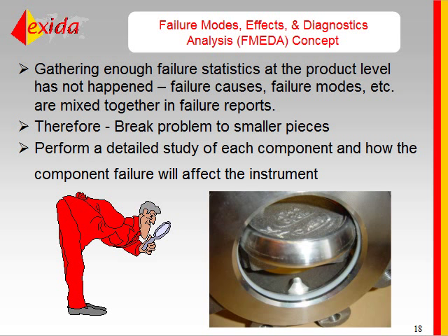Now, the concept of an FMEDA is pretty simple when you think about it. If you have a product like a pressure transmitter or a valve actuator assembly, you could get the failure rates and failure modes from good field failure data records.